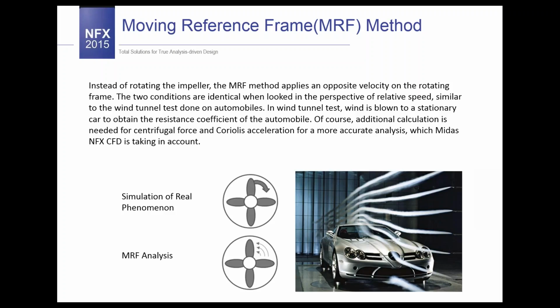actually you have rotation, so you have to consider centrifugal force, Coriolis acceleration and other things. Midas is taking that into account, but basically this is how it works. When you do sliding mesh, you have the real phenomenon, so you simulate the rotation. When you do MRF analysis, you are actually simulating the air rotating around the blade, which is fixed.